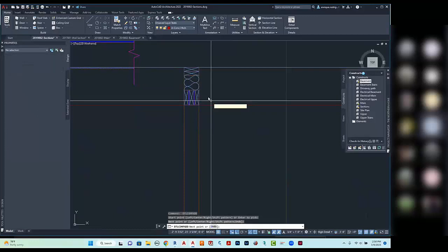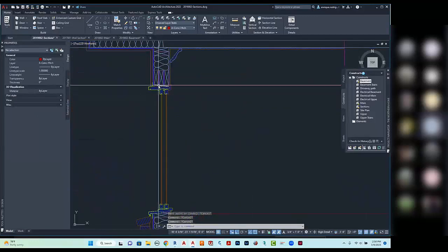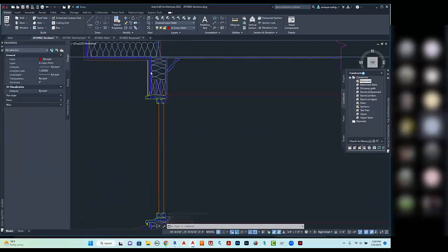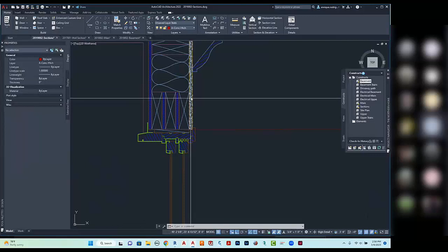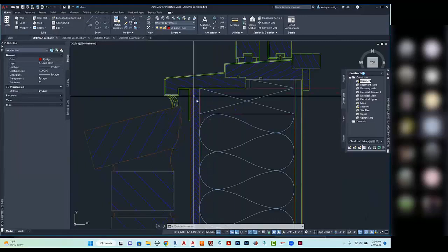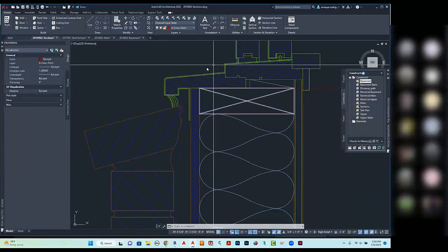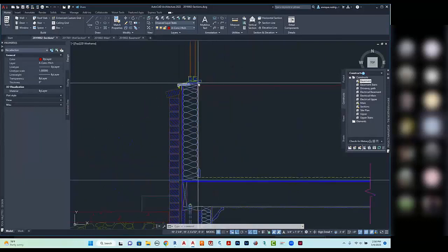And finish it up in there. All right, now this is where we can actually go ahead and put the plywood starting on this side, and we're going to go ahead and put the drywall on the inside. Again, the plywood should go up to the bottom of the window that we're going to be setting in, which means it's going to line up with the top of your 2x plate.